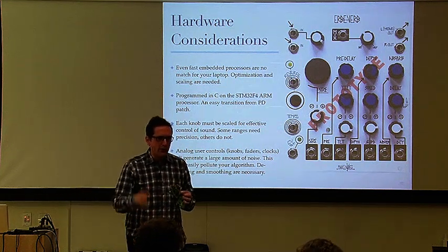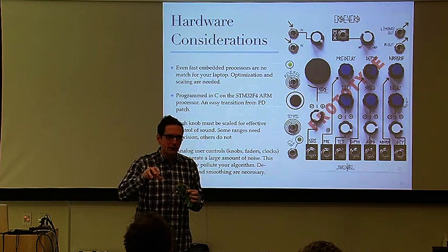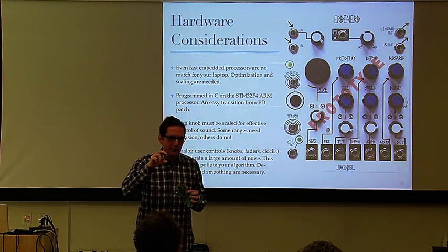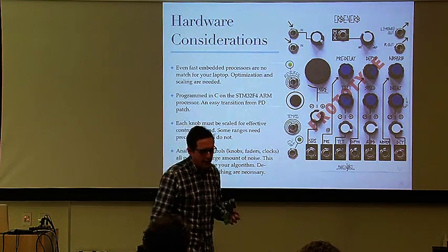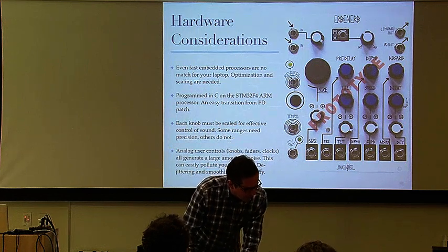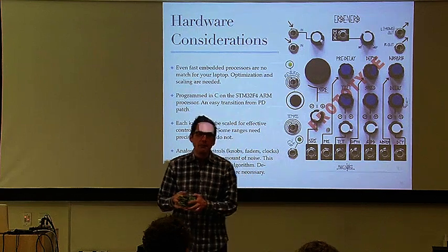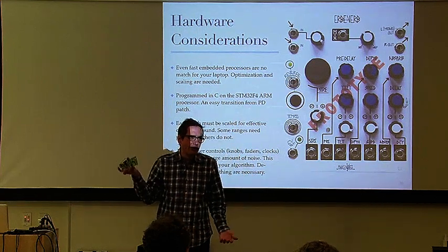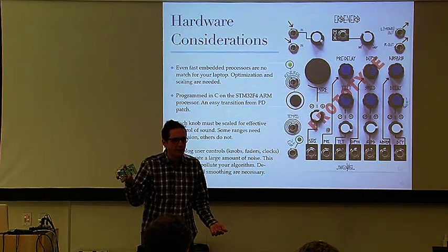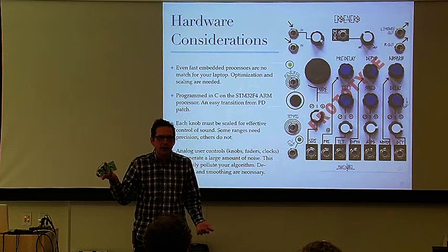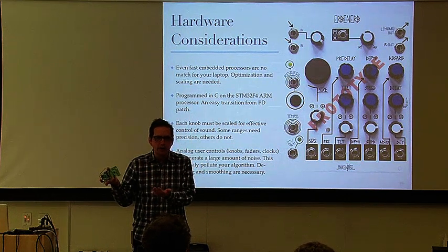So it's a matter of tuning those two filters and hysteresis to keep it in control. That was the main engineering task with this. Otherwise, programming embedded processors, it's all C code. You're actually using GNU CC. It's very easy. The code pretty much goes straight over.